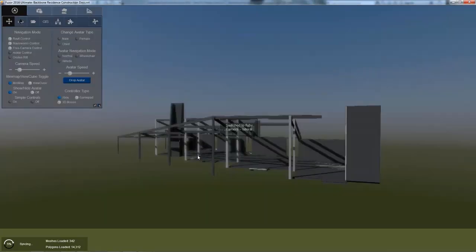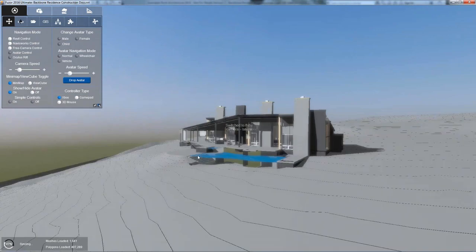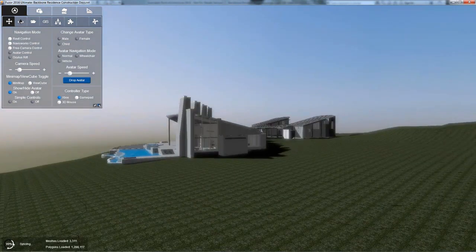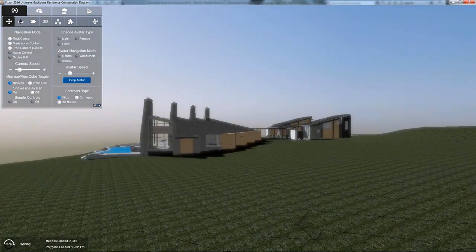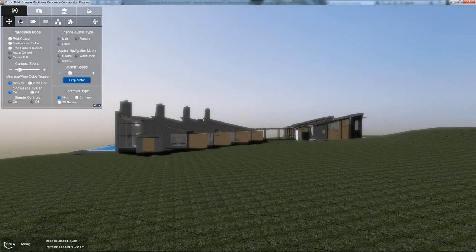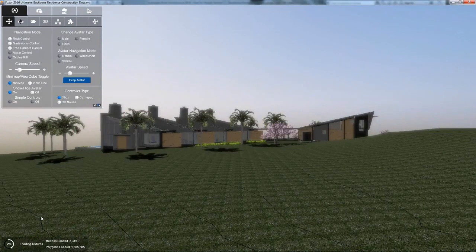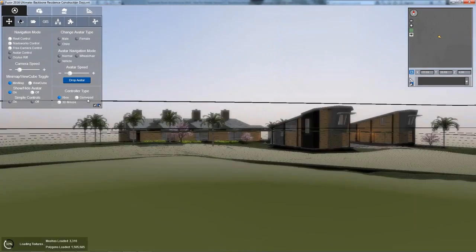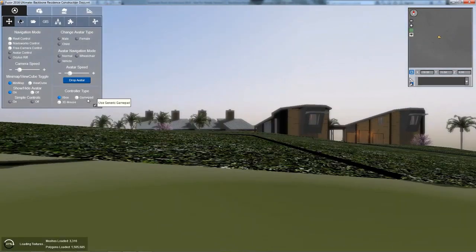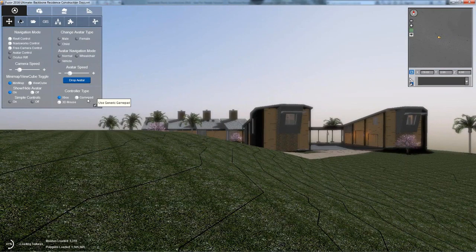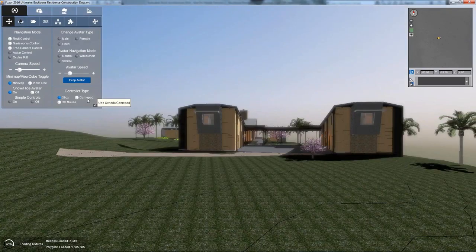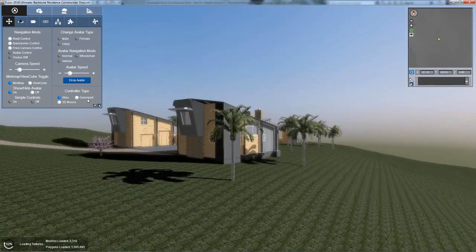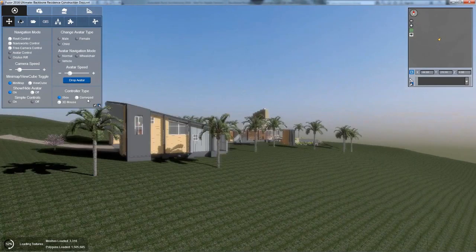So you'll see that when this kicks over, first thing it's going to do is you're going to see a synchronization bar in the bottom. The first 100% is synced over your geometry. Once it hits the second 100%, that'll mean all your textures have been linked over. Also, if you have custom views, custom 3D views, Fuzor can also handle those specifically by different views. So if you have a couple of different setups, I can show you an example of that later if you'd like, but you can actually select a separate 3D view and it'll load that instead with that specific setup.